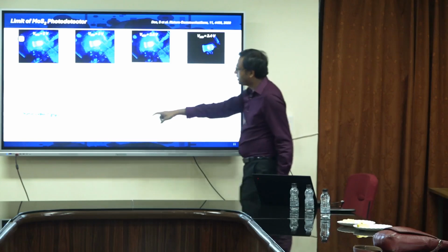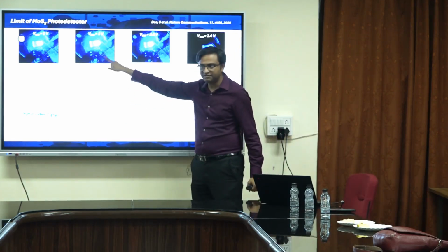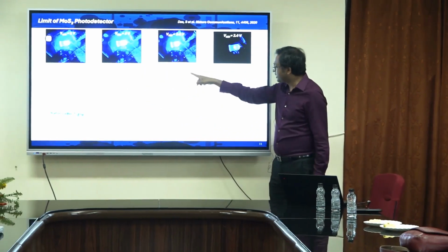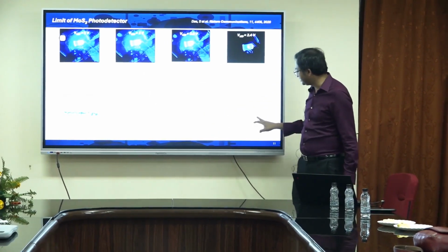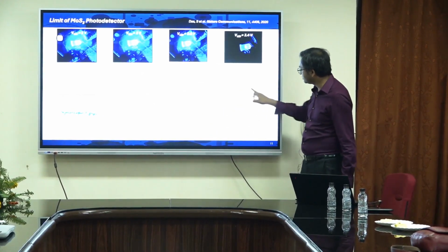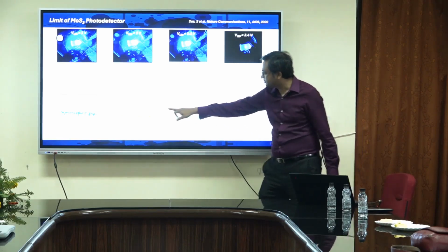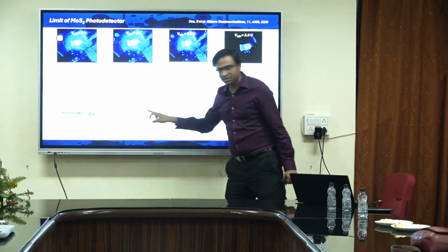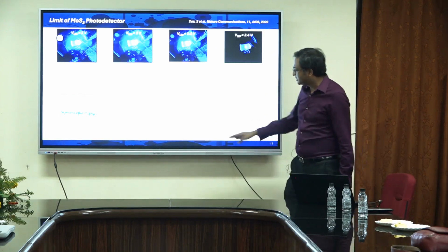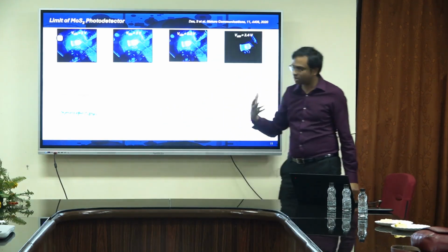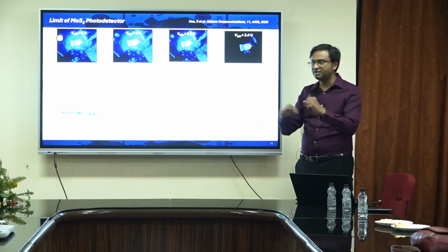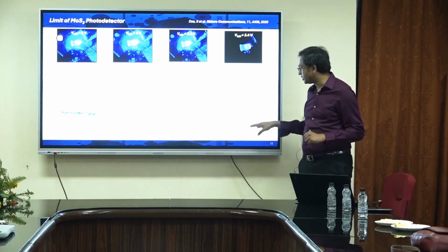So here is a peak. That means I can detect that there is information coming, right? But once it becomes dim, there is no peak at that frequency at which the light is going. This peak is an artifact, but you see we have lost this peak. You see that, right? And this is the background noise, which is because of the dark current, or whatever background information is present, that gives me that noise floor, right?